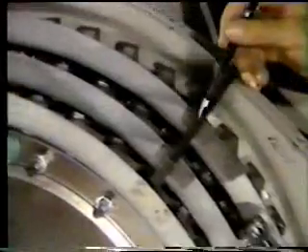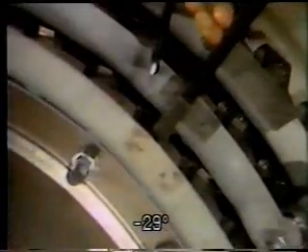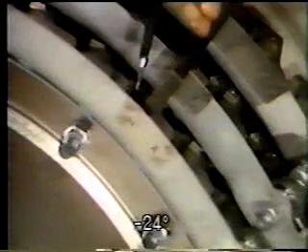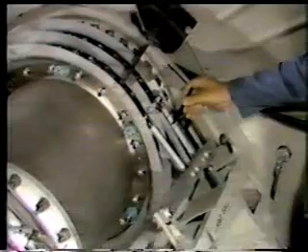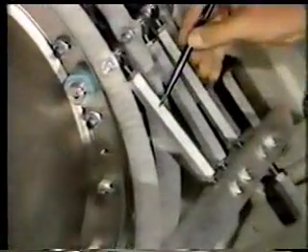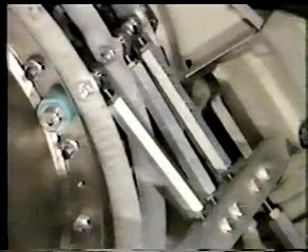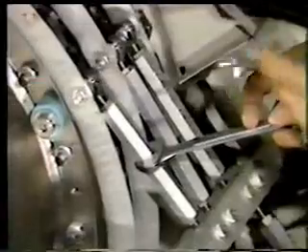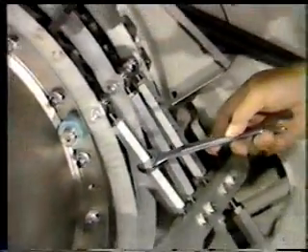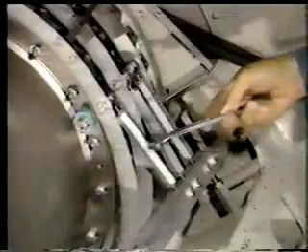They should read -29 degrees and -24 degrees respectively with the actuator retracted. The first and second stage stators can be adjusted by rotating the turnbuckles. After you have made all adjustments, tighten locking nuts on the turnbuckles. Make sure that each turnbuckle will rotate freely on its bearings. Retract the actuator and turn off the oil supply.